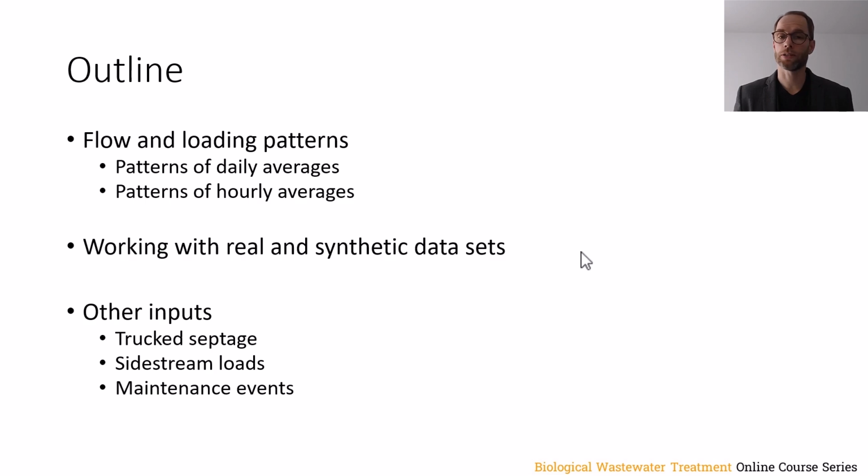Side stream loads. If we're doing dewatering of digested sludge on site, then the reject water represents a side stream load that we might want to be accounting for dynamically, as well as maintenance events. So for example, when a bioreactor train is taken offline because we want to do maintenance or we want to clean the aeration diffusers, a very common event that we might want to be accounting for in our simulation dynamics.